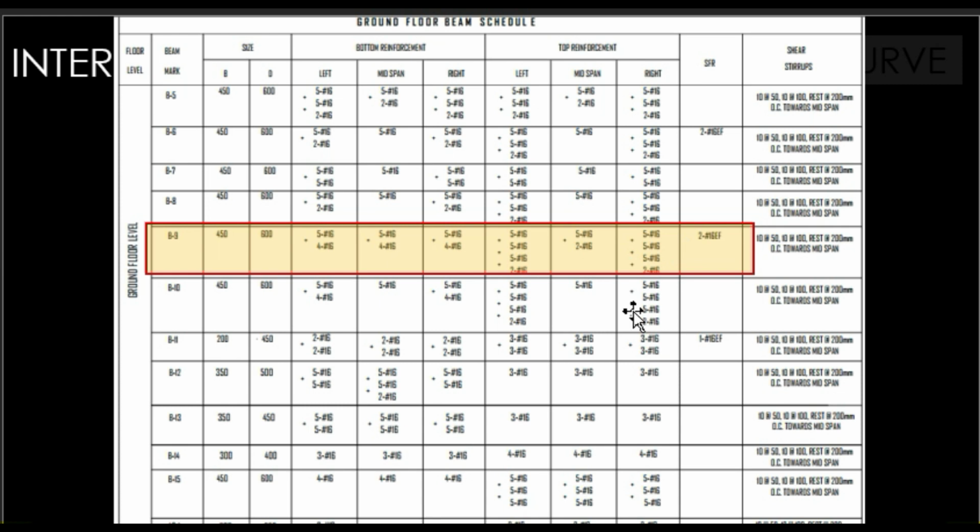That is, the number of continued stiffener bar at the top is taken 5 plus 2 along left and midspan and right support. Therefore, the remaining 3 is added to 5 and 2, which makes it 10 for each support.